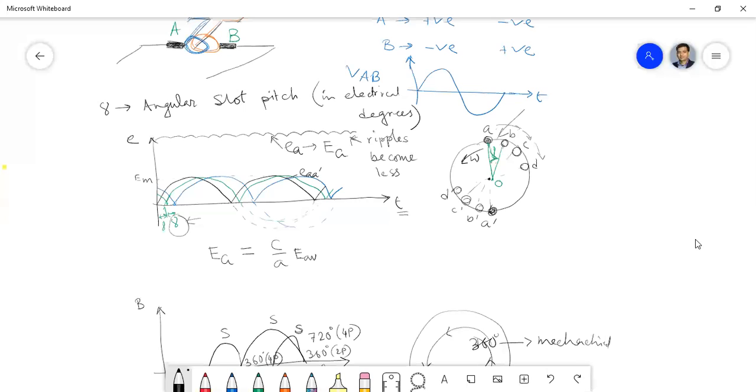So that is the advantage of using the distributed coil. We get the induced voltages with different phase angles. If we sum up all these rectified components of coil contribution, the ultimate voltage we get is almost ripple free.